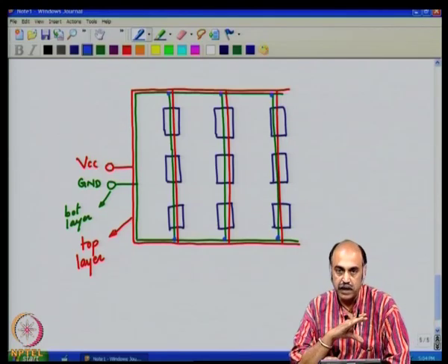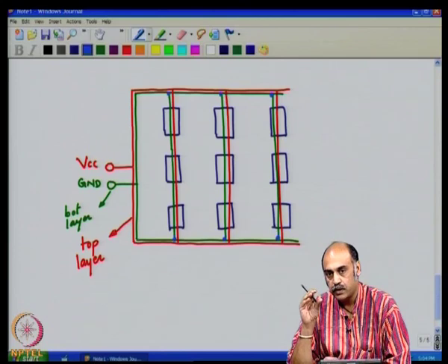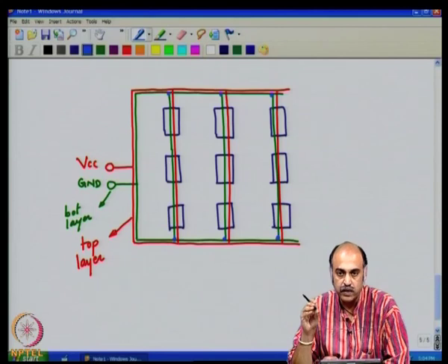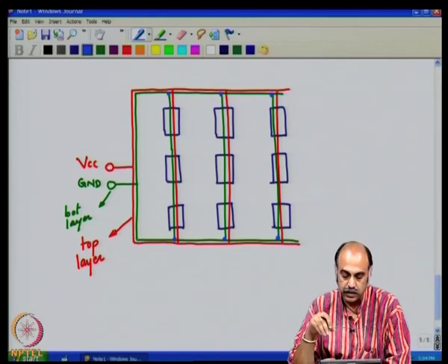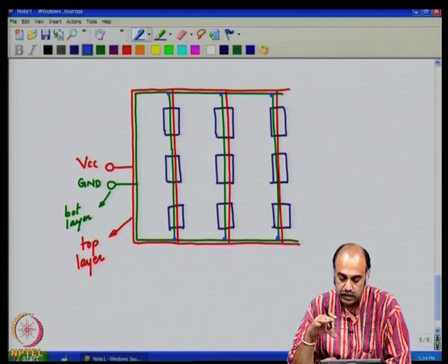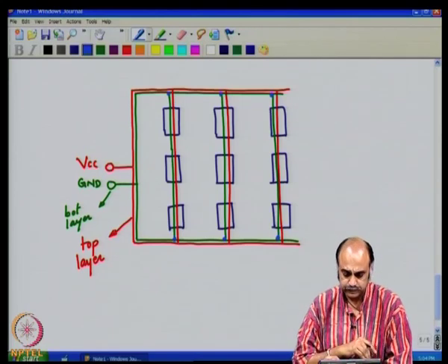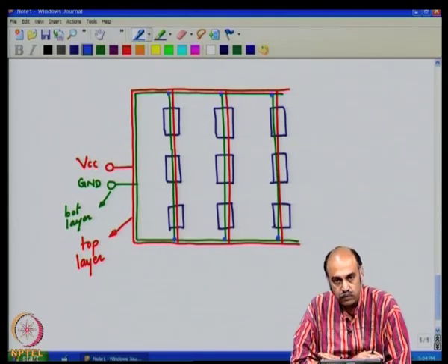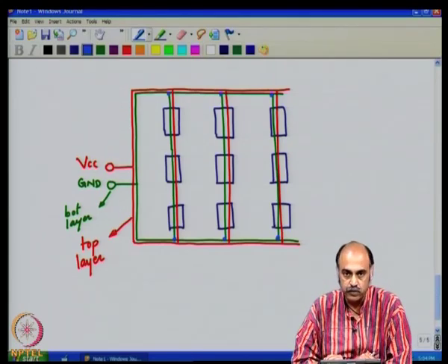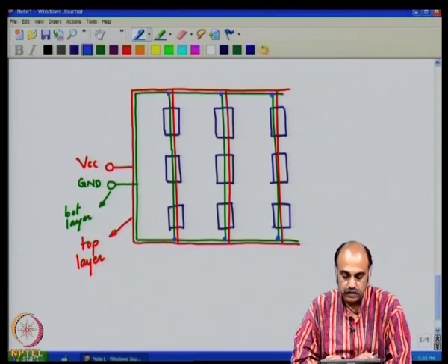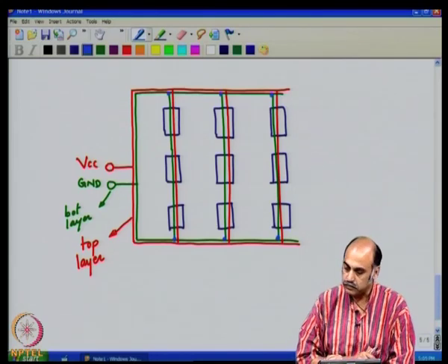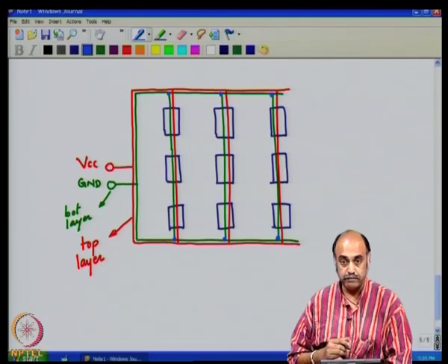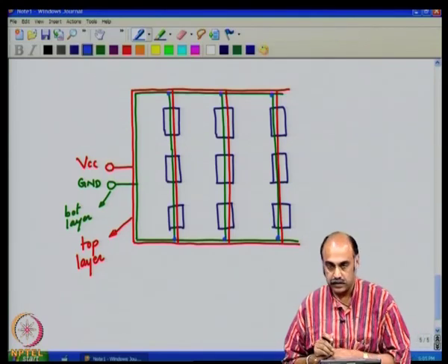So that you are maintaining a capacitance, maintaining the capacitance for every centimeter run of the track length, and thereby having a good distributed capacitance. Of course, for the case of multi-layer boards, you are dedicating one full layer for ground and one full layer for the supply, and thereby you could have much better capacitances than before.